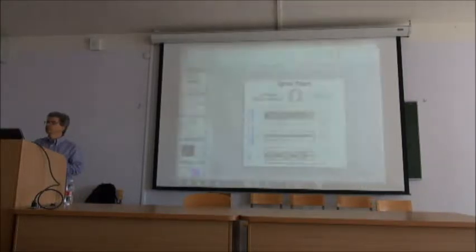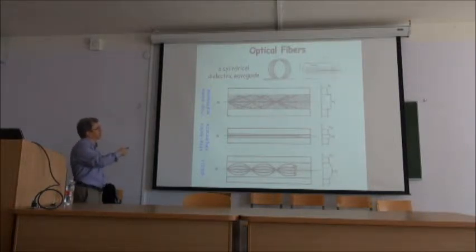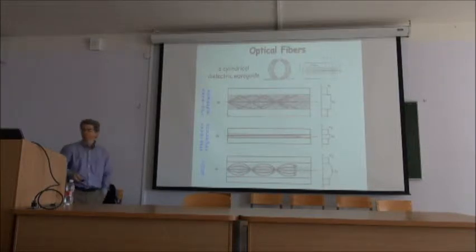And so we start our lecture today with optical fibers, and they come in several flavors. Essentially, an optical fiber is a cylindrical waveguide. It has more symmetry than the rectangular one, and it's a core surrounded by a cladding. Depending on size, they can have multiple modes inside the structure. And when they have a very small size, we learned that we may get a single mode, and they may come in step index or also in graded index.